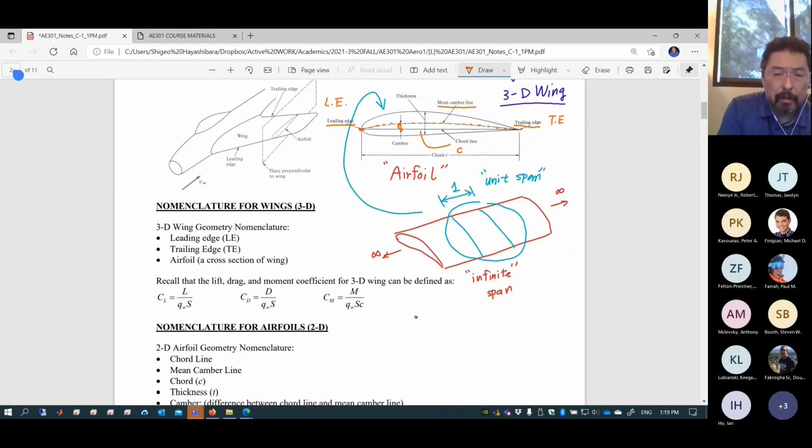Now, obviously, we have a positive camber, or we can have a negative camber. Negative camber can be understood as upside down positive cambered airfoil. This is like, have you ever seen this? Like Zach, I guess you know this kind of thing. Where did you use? On, you know, like wings on cars and stuff for downforce. That's right, race cars. Race cars rear wing.